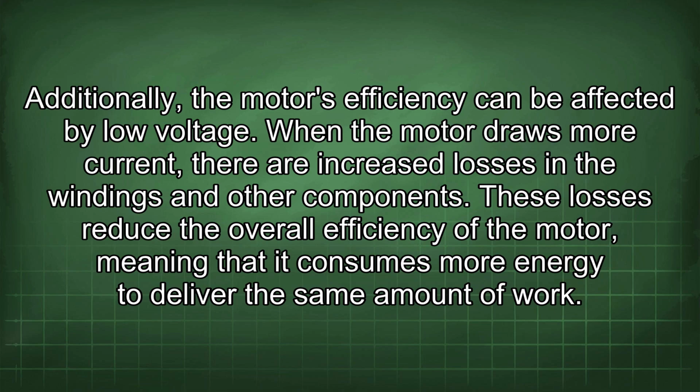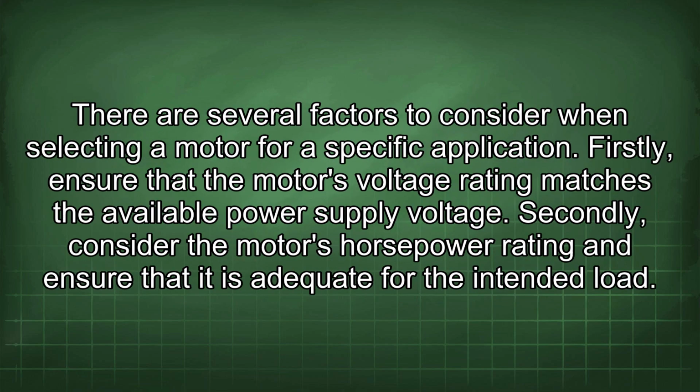Additionally, the motor's efficiency can be affected by low voltage. When the motor draws more current, there are increased losses in the windings and other components. These losses reduce the overall efficiency of the motor, meaning that it consumes more energy to deliver the same amount of work.